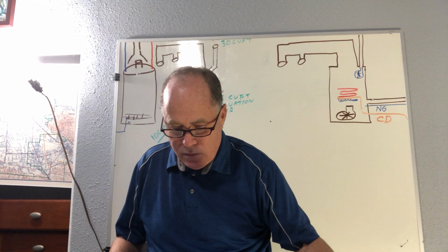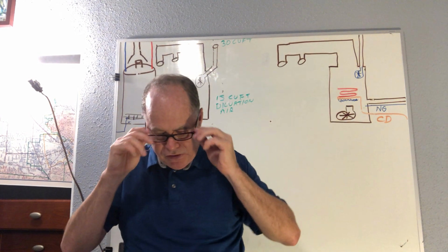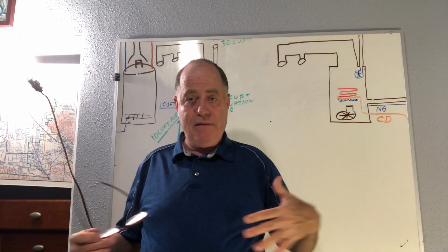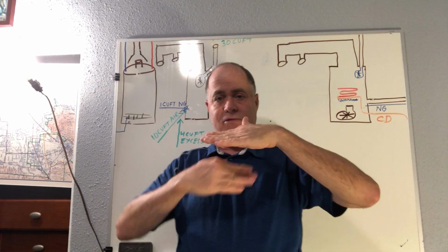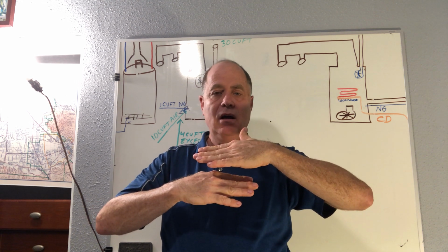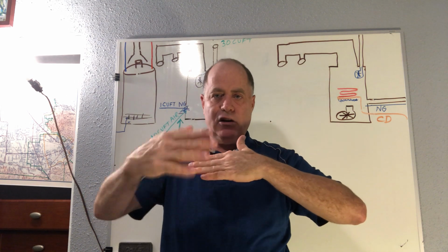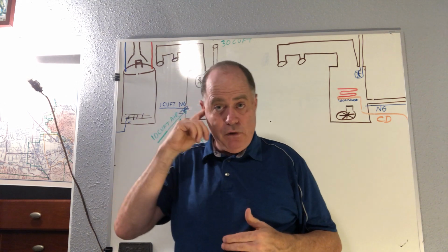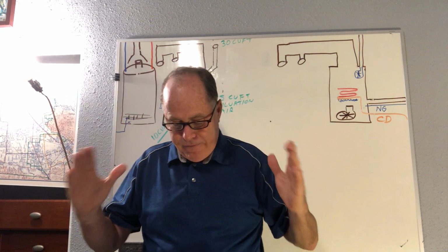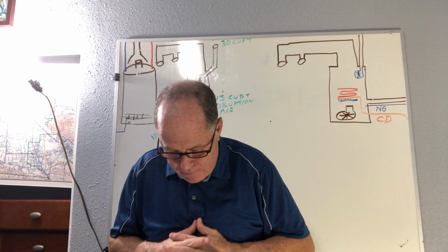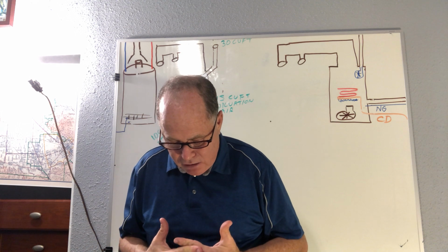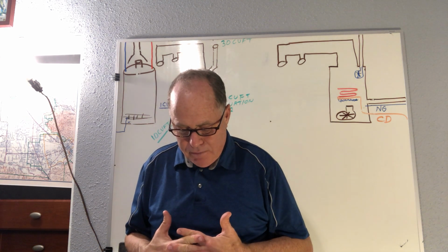On louvers and grills, if you are taking air from the outside and you have louvers and grills, which makes sense, a lot of times you'll have louvers or grills so that you're bringing air in, but rain or water can't get in, right? And you're calculating the area that you need for fresh air. It is assumed that wood louvers have 25% free area and metal louvers have 75% free area.